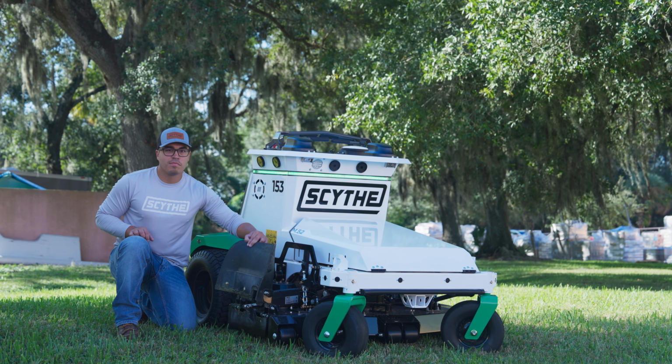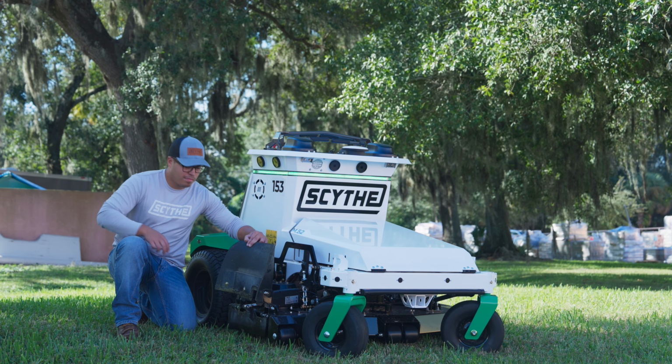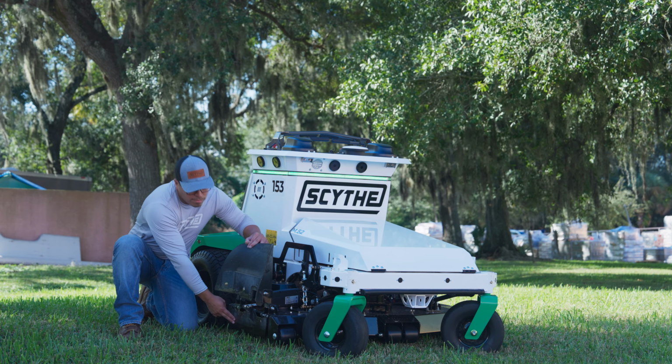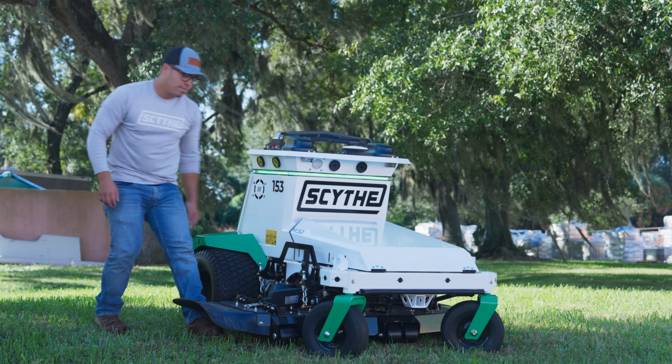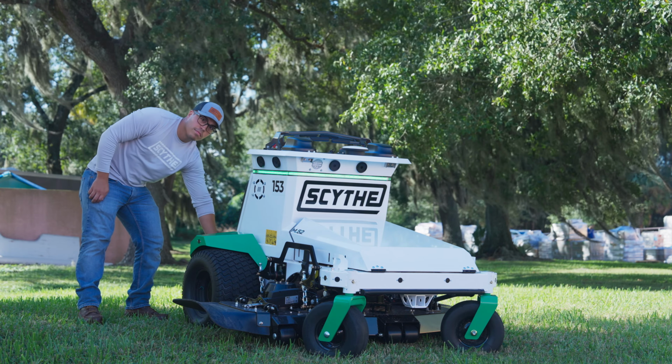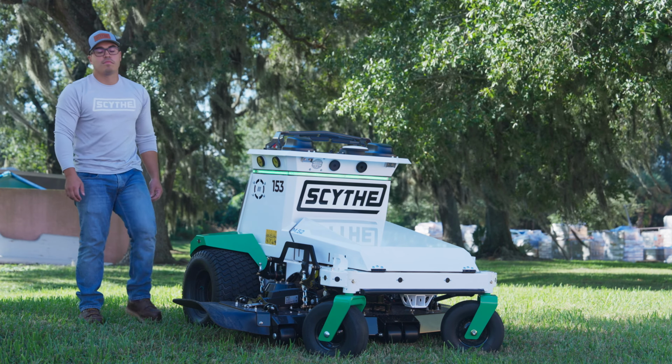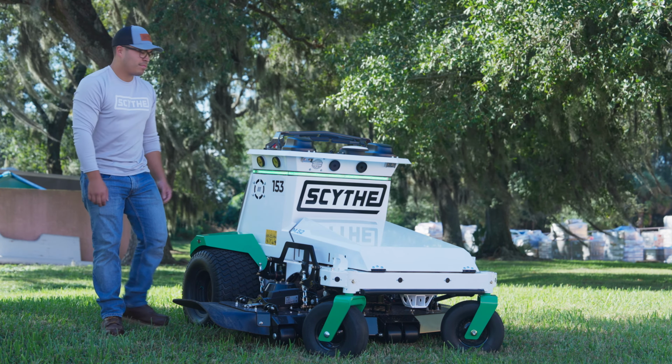There is a chute blocker that can be adjusted manually from the control panel when in drive mode, and that automatically adjusts when in Scythe mode. There are tie-down points at the four corners of the machine for safely tying down the machine in transit. Any tie-downs used should be rated for a minimum of 1,500 pounds.